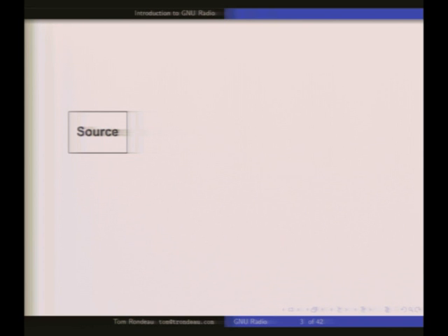So you got to come in from somewhere, and GNU Radio offers you the ability to pull in data from all sorts. This is just a short example, so you could just read stuff from a file. You could bring it in from an audio source, like a microphone. Other programs, so you can tunnel messages through into GNU Radio from another application layer. Or radio hardware, so if this is a receiver, you have a radio receiver that's acting as your source of samples that GNU Radio is then going to act upon.